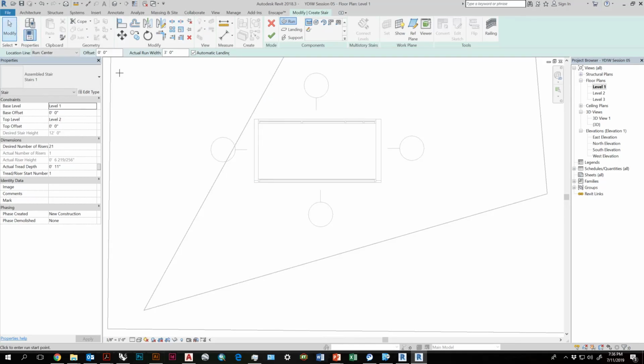Stairs. So that's a whole thing. Revit stairs are kind of finicky. It gets better with each version. But what's great about Revit stairs is that they automatically do all the necessary calculations. It tells you exactly how many stairs you need, and also how many stairs you need before you need to put in a landing. And then you can place a landing and continue the stairs.